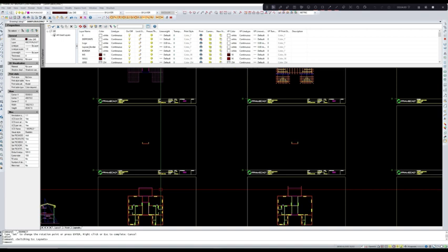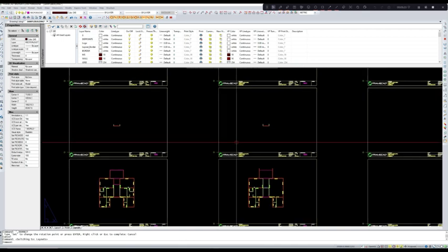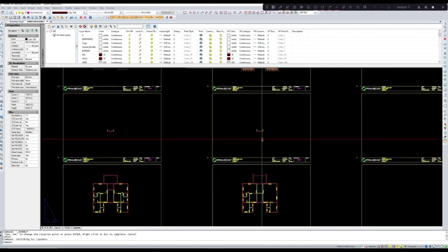So at first floor we do not require double stud, back to back stud, for load bearing wall, because they will be carrying trusses which are very lightly loaded. So actually we should change the truss stud type in that. But this is a tutorial, so that will make the process long, so we are not doing it. So you can do it with the list command.